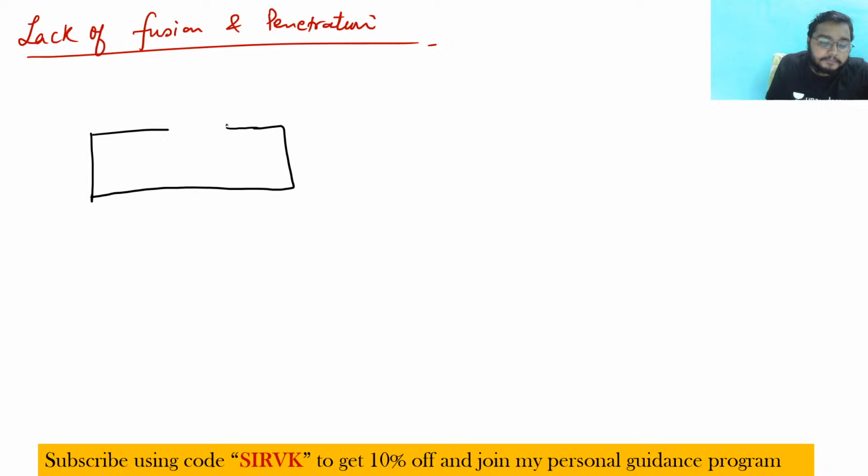Suppose you get this kind of weld bead. This is because fusion is not happening in a proper way. And see, this weld bead is not properly penetrating the workpiece. These kinds of defects give rise to lack of fusion and penetration.